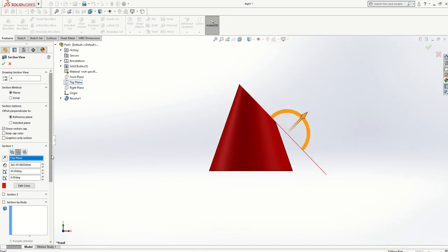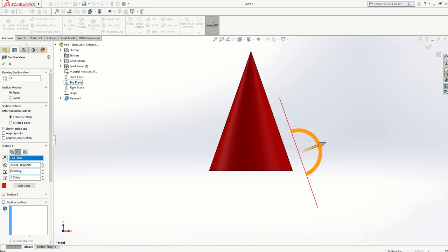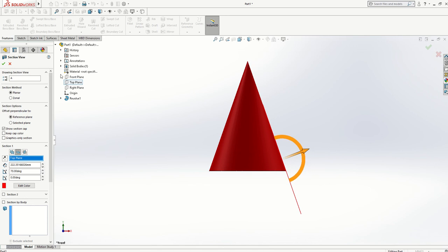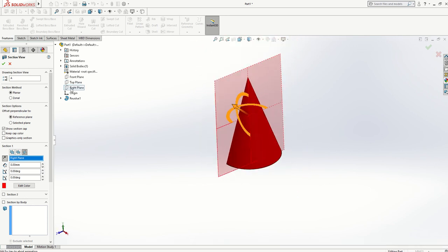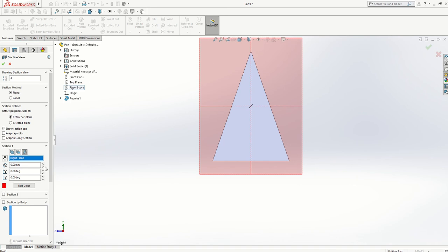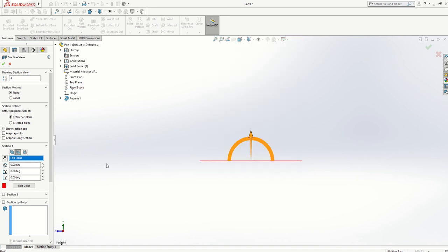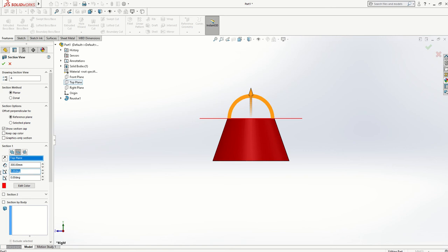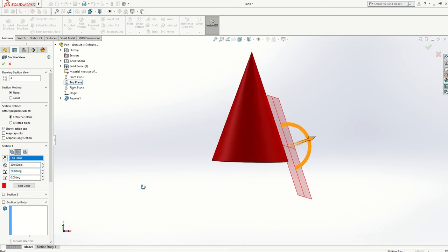Now, the last one we look at is a parabola. If I wanted to get a parabola from a cut section of this cone, I'll make a cutting plane that's parallel to the outer generator, or the outer side, of my cone. We see the very edge line of my cone here on my elevation, and I put a cutting plane that's parallel to it. I bring this around and view from the right hand side this time. Sorry, one second.